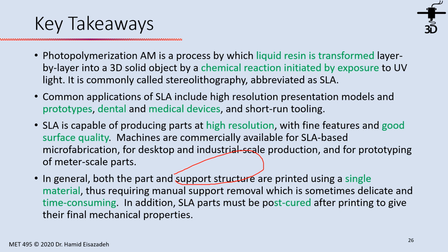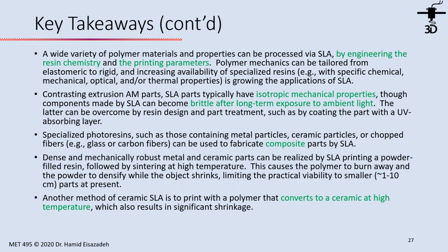Therefore, it requires manual support removal. Sometimes it becomes delicate, and it can be time consuming. And also you need post curing after the printing in order to have good mechanical properties.